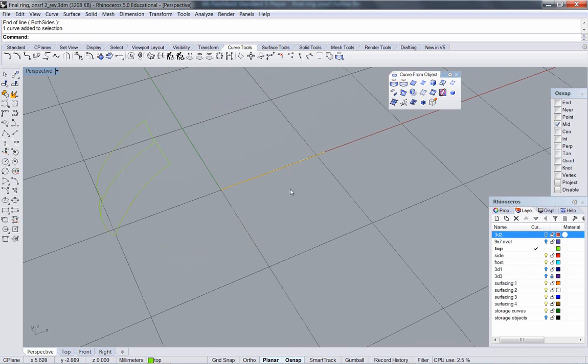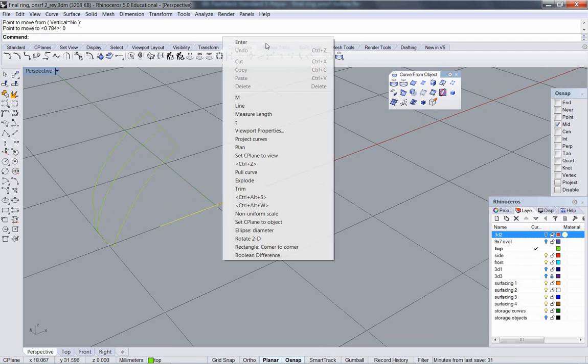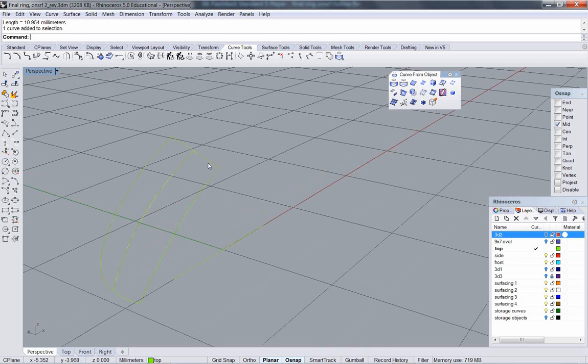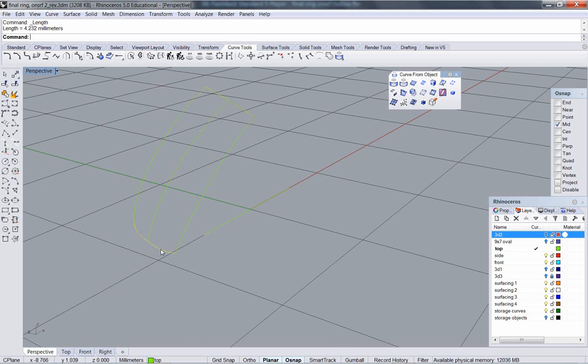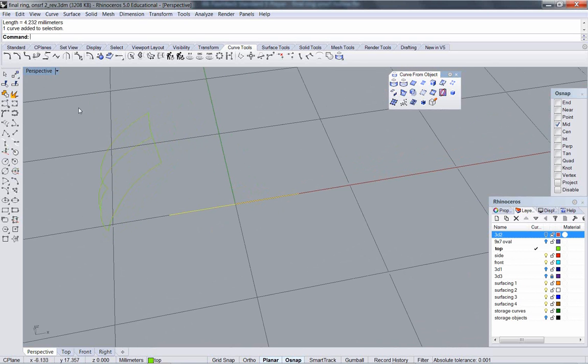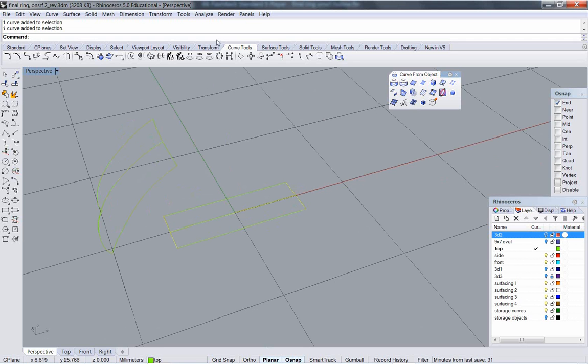Go ahead and move that into the center. Confirm length. They're the same. I want to know how long this is. 4 millimeters. 4.2 millimeters. So we'll make it 4.1. Offset both sides, 2.05. Put a curve at the end. Analyze the length of those.